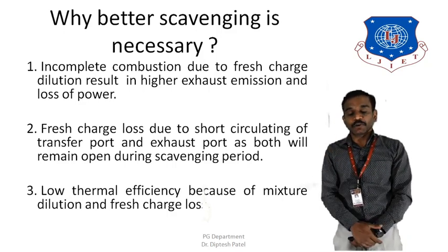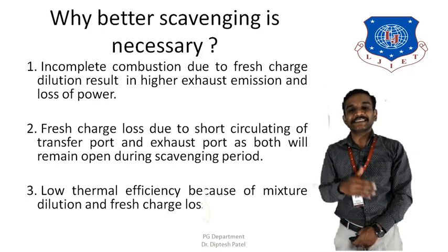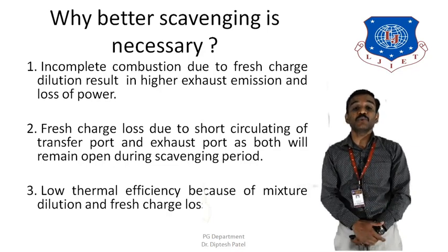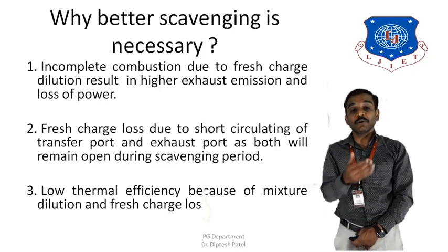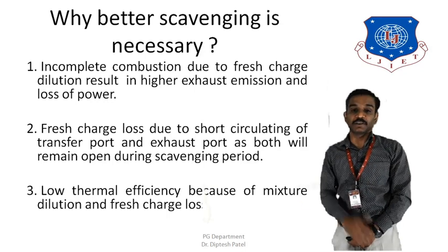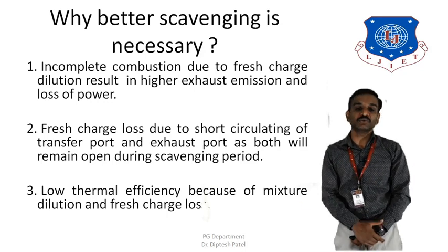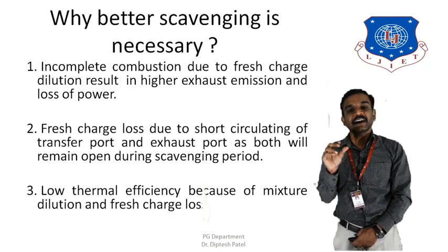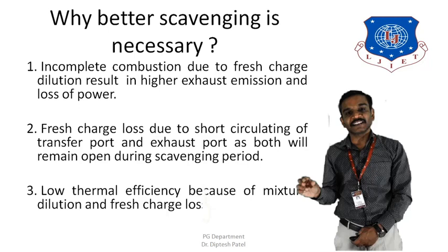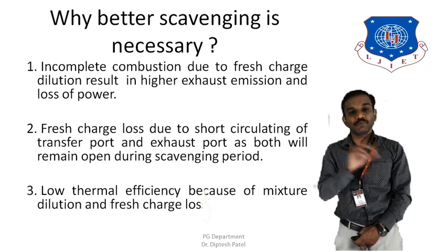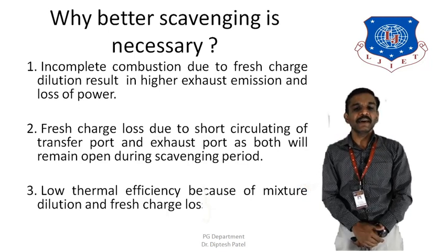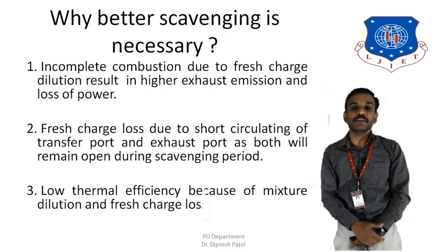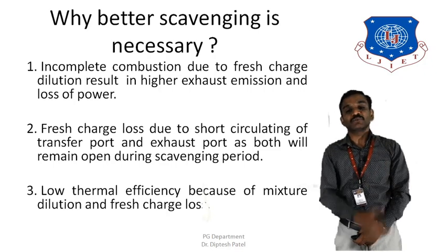In the scavenging process, if it cannot be completed properly, then there may be a chance of losing the fresh charge along with the gases through the exhaust port. This especially happens in a two stroke engine, because for a certain period of time both the transfer port and the exhaust port remain open for a short period, and there may be a chance that the fresh charge coming in from the transfer port may leave through the exhaust port.